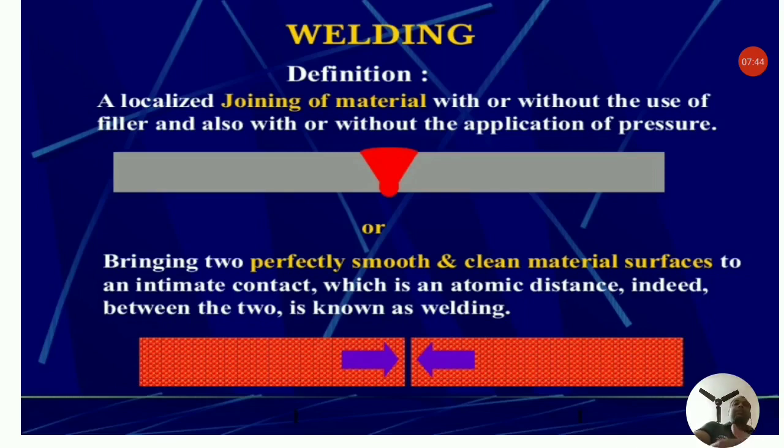Now adhesives are capable of providing the necessary strength to withstand the applied loads for some applications as well. The most commonly used adhesives are classified as thermosetting resins, thermoplastic resins, silicone resins, and elastomers. Out of these, the elastomers, which comprise synthetic and natural rubbers, are elastic in nature and therefore cannot be used for structural applications, since they lack the necessary rigidity. However, they can be mixed with the thermosetting resins to reduce the brittleness and provide toughness for shock resistance as well.